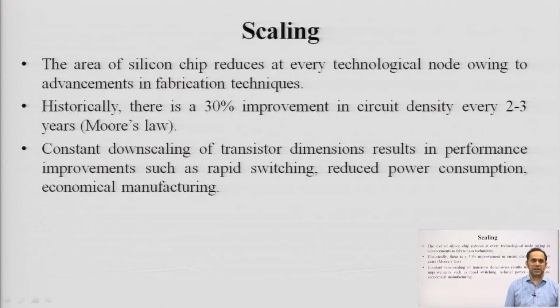The critical dimensions, the width between different transistors, the length of the channel, the width of the gate, the voltages, the doping, all have been scaled down or up in such a way that you can put more and more transistors on a per square millimeter area of silicon.